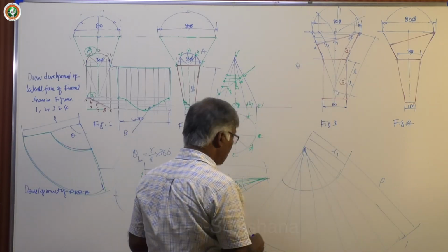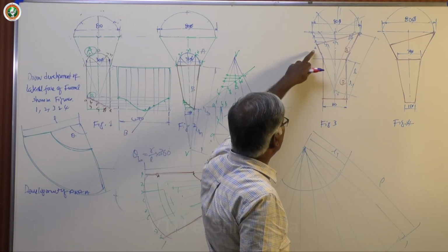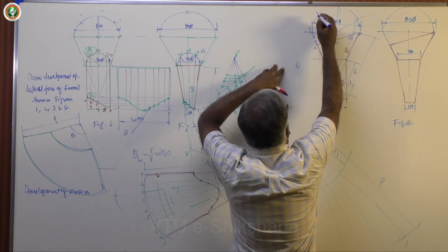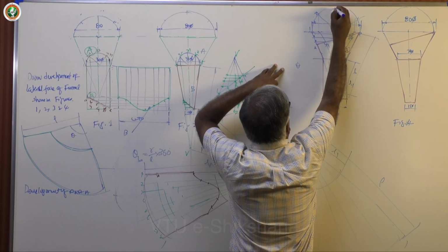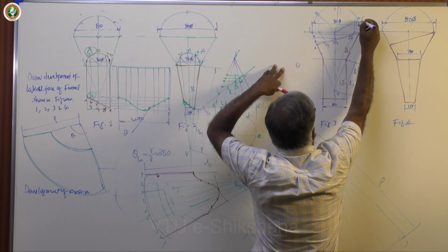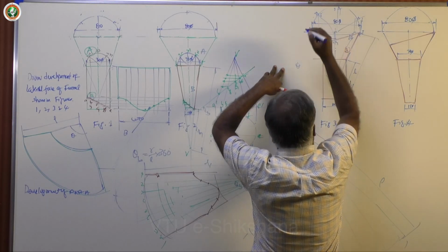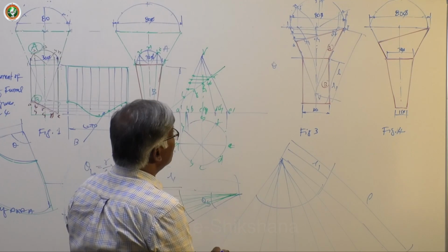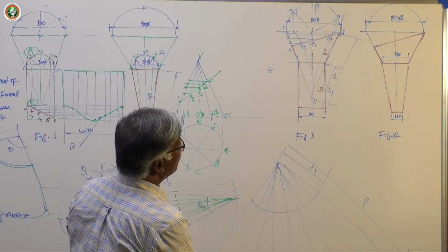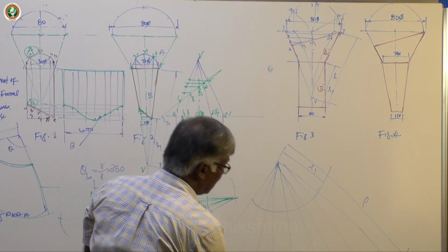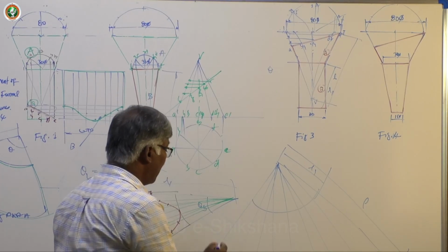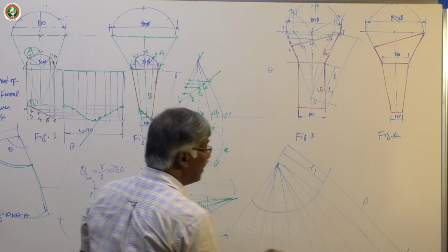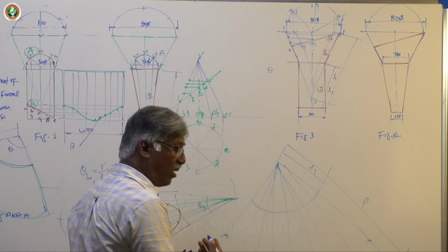Again you can draw arcs. See, here the first point is 1. You can say this is 1, this is 2, 3, 4, 5, 6, 7, 8, 1. The 5th point is touching this section plane, and here for 1 you take this distance from V, okay, this point and this point, or draw a full arc.